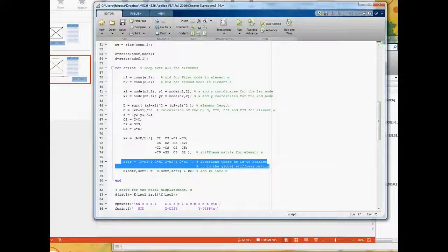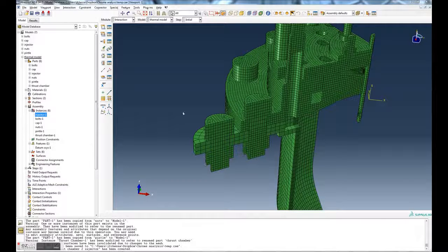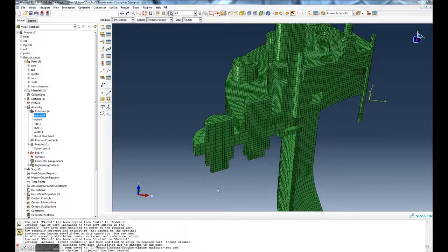And there it is. And now if we continue through all the elements until we get out of the element loop, now you have a fully formed stiffness matrix. That's the fully assembled stiffness matrix with all 6 elements in it, right? All done the same way, but through an element loop, okay?